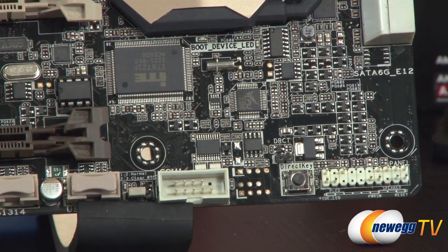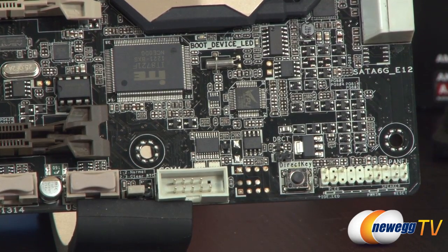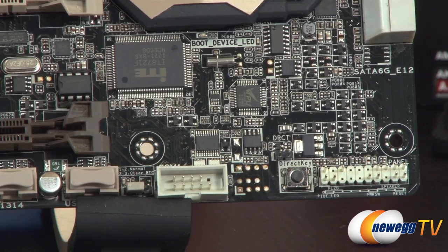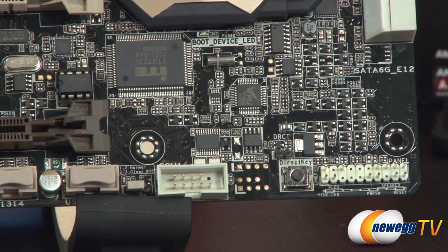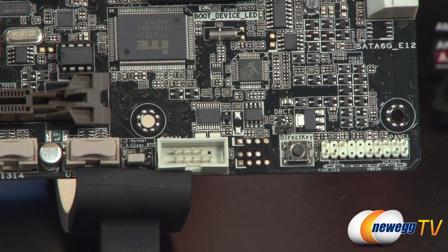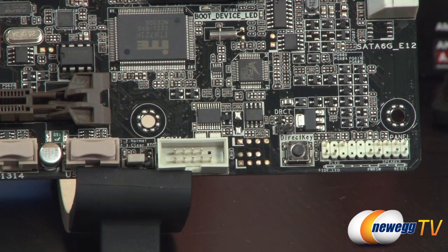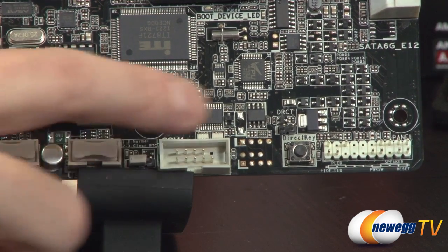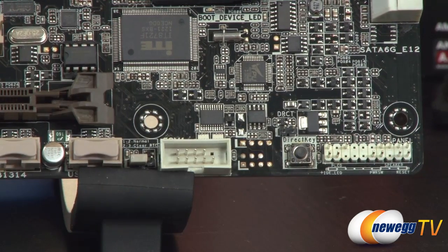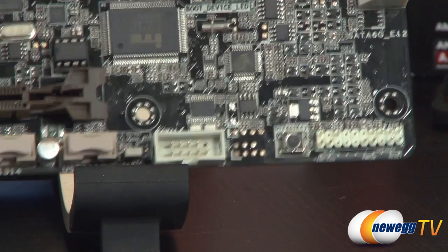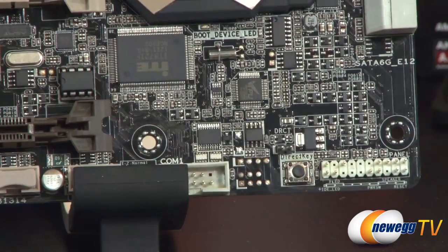You'll typically have a power button, a reset button. You'll have LEDs for power and hard drive activity. And then you'll also have a speaker connector, which may or may not be included with your case to have an actual speaker so you can listen to post codes. One thing to keep in mind here is that whereas your power switch and your reset switch are not directional, so you can plug in those little pinouts either way, the LEDs are, so you should pay attention to positive and negative markings on your LED connectors.